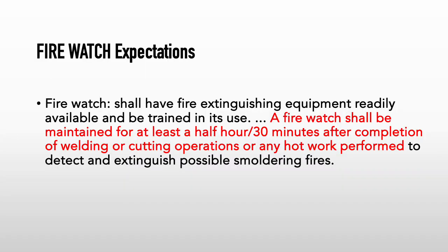These are the expectations for fire watch. It reads as so: shall have fire extinguisher equipment readily available and be trained in its use. A fire watch shall be maintained for at least half an hour, or 30 minutes, after completion of welding or cutting operations or any hot work performed to detect and extinguish possible smoldering fires.